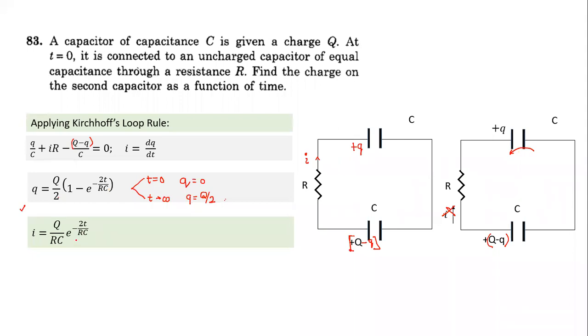So it makes some logical sense, and we can derive it also, and the current value comes like this. Current also, this is negative, and the derivative is positive. Yes, this is the direction of current, and the charge transfer will have an exponential decay. The current also will decrease exponentially with time. What is the time constant? RC by 2.